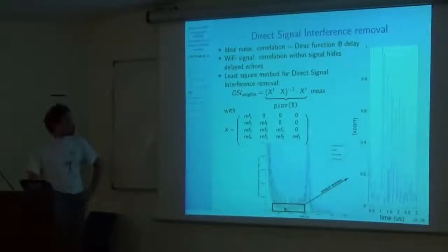So what you need to do is to try to find delayed copies of a reference. So here is my reference measurement, and then I take delayed copies, by 1 time slot, 2 time slots, 3 time slots, each time slot being one sampling period, and I try to find: is this time-shifted copy of a reference found in the measurement channel? If you're familiar with least square measurements, it's called Pseudoinverse, a function in MATLAB that is quite efficiently implemented. You can demonstrate this is how Pseudoinverse is working.